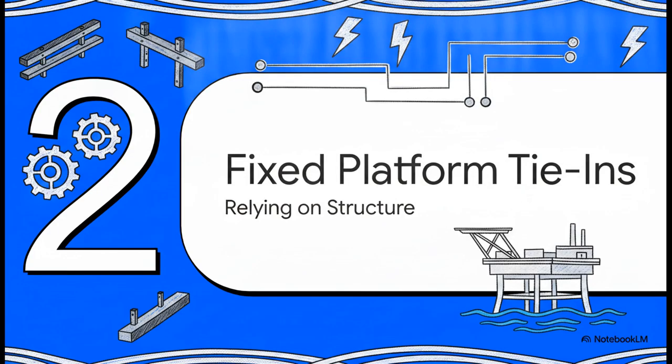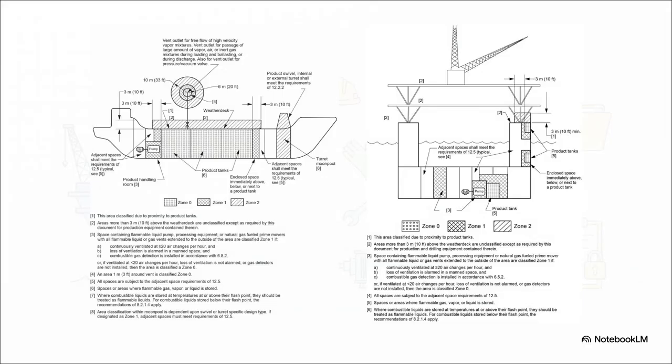Moving on to Section 2. Fixed platform steel tie-ins, removing the hull, relying on structure. Contrasting these two units side by side really tells you almost everything you need to know about why their documentation differs. On one side, we have that ship-shaped FPSO hull. On the other, we have a fixed unit, like a tension leg platform. This fixed platform stands on legs, tendons, or a steel jacket. It completely lacks a floating ship hull designed for bulk oil storage. Because of that major structural difference, that heavy marine class layer we were just talking about, it mostly disappears.